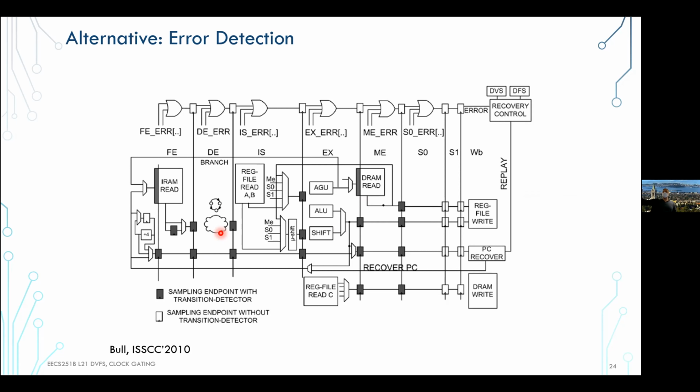But okay, on the other way, right? If you're going to higher performance, you want to do what? What happens if you keep the voltage, but you increase the frequency? Does that work? I mean, you want to increase the frequency eventually, but if you're at a certain voltage, can you just increase the frequency? Likely no, if you did a good design, right? Because you were kind of close on the slack. You're riding that curve reasonably well, right?